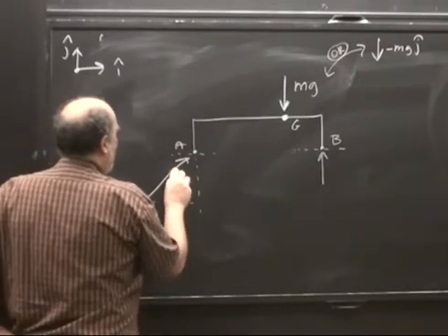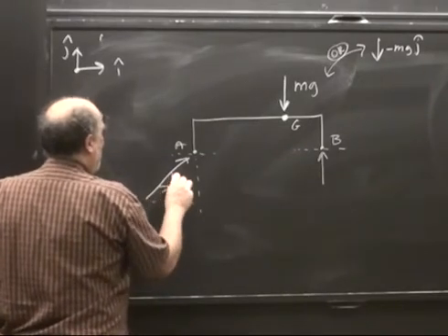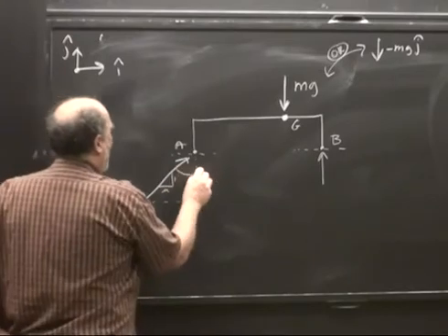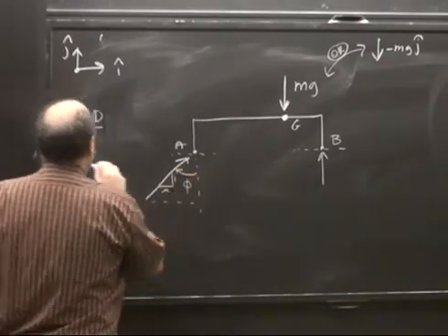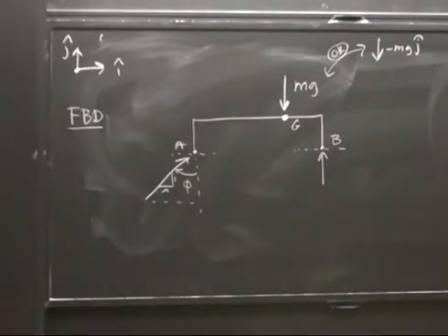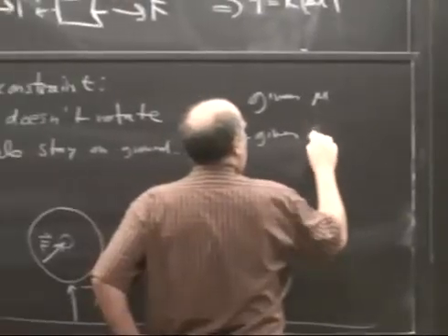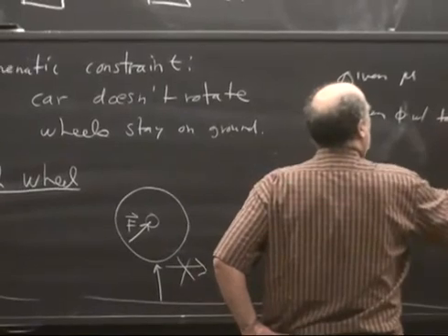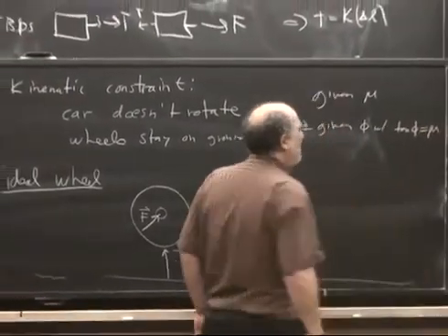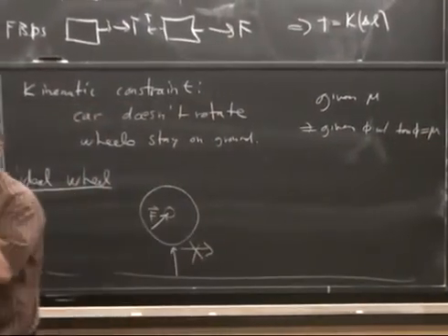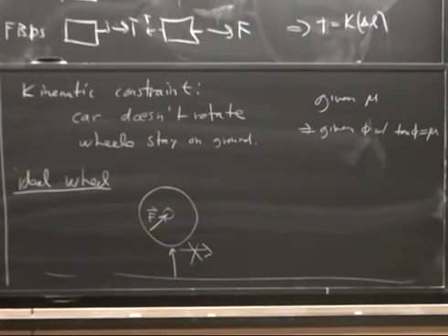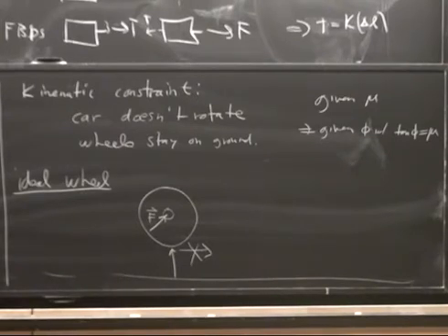And I can either say the ratio of the sideways force to the vertical force is mu to 1, or I can say this acts at a friction angle phi, where I'm given phi with tan phi equals mu. It's just an equivalent way of giving the coefficient of friction to give the friction angle. And now I've got a free body diagram of this thing, and I want to figure out what's going on with this. So any questions about what I have so far?